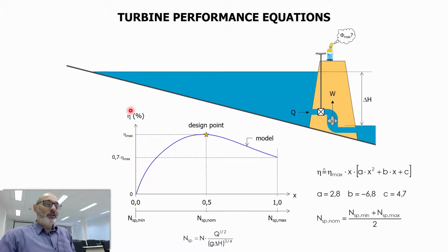So the turbine: how do we control it, and how can we model these performance or efficiency curves? What we can do to control it is that the operator can increase or decrease the flow rate that is being used to generate. So this can be controlled. You open or close this valve, and you increase or decrease this flow rate instantaneously. Of course, during a year this has to be equal to the average flow rate, but instantaneously you can vary it. So Q is variable or controllable.